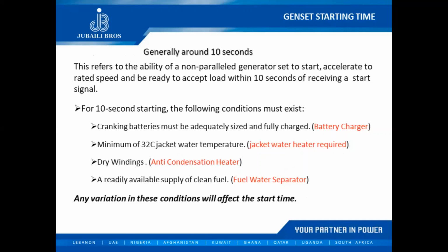Now, genset starting time. Typically it's around 10 seconds. This refers to the ability of non-paralleled or standalone generators to reach the rated frequency and rated voltage within 10 seconds from receiving the signal. Now I'd like to tell you where this 10 seconds came from. It's not very accurate when we say that the genset should reach its rated voltage and rated frequency in 10 seconds.